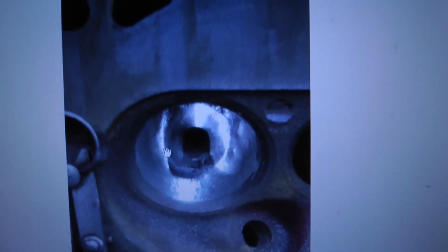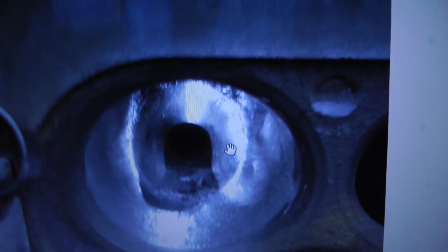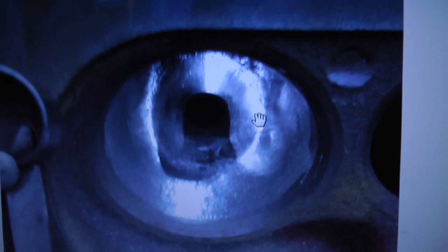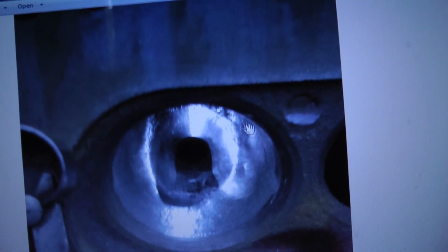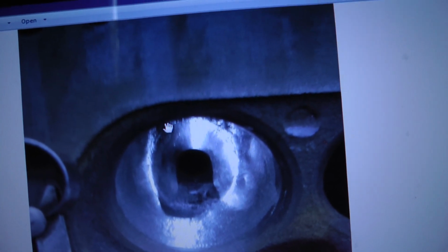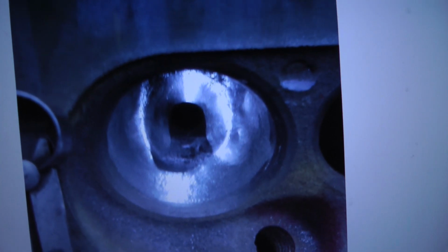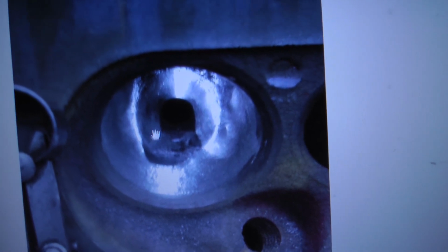Last three. Here's my intake bowl. You can kind of see the inside spring caliper. You use that to go from the outside diameter of the valve stem. You can see where I cut away the valve guide boss and kind of shaped that. It's a little more aerodynamic. I still have to do work on the short turn radius. See, the last video I had the cutouts open, and now I don't have that.